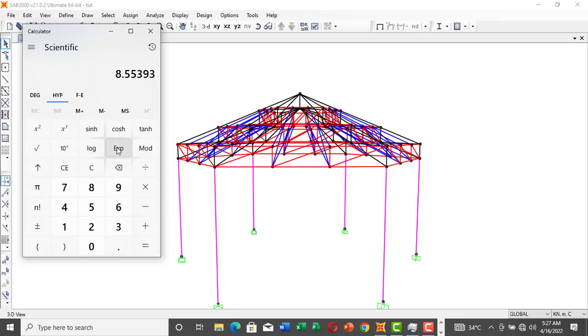So at every joint there, I'll be loading it 9 kilonewton. And for the frame of the roof, I will load it. That's 0.12, that's 120 mm, multiplied by the thickness, which is 10 mm, 0.01, multiplied by the unit weight, that's 77. So that is about 0.0924 kilonewton per meter. This is not in kilonewton, this is kilonewton per meter. That is a UDL, so I'm going to load it as UDL. So I can exaggerate this to be 1 kilonewton per meter square as well. Alright, so that's good enough.